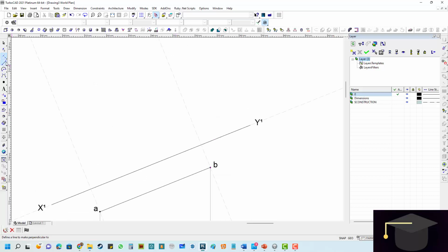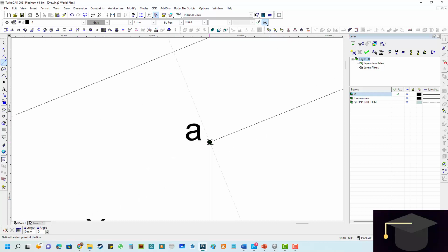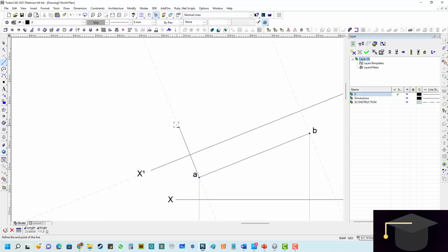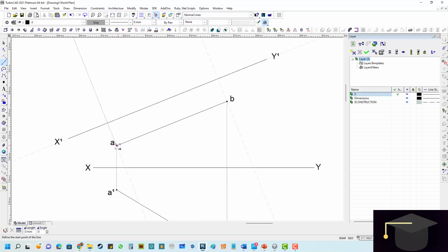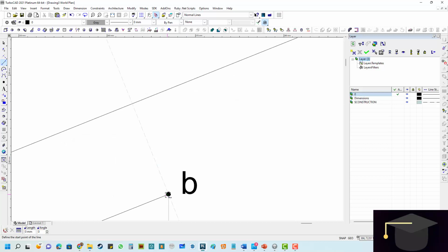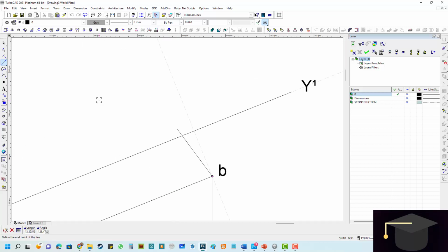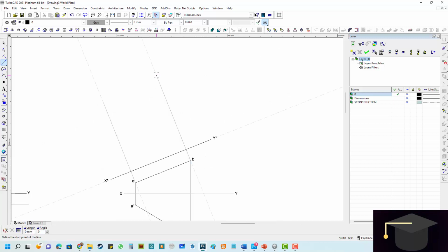Now, just so that it's visible, I'm going to use the line length tool again and change the color to gray because it's a construction line. Then I can go back to the reference point. I already have this angle at 90 degrees, indefinite in length. I'm just going to project that construction line 90 degrees over the X1, Y1, and also 90 degrees with line segment AB. Then I'm going to do the same with point B. I'm going to go there, reference point selected, and then indefinitely extend that 90-degree projection.